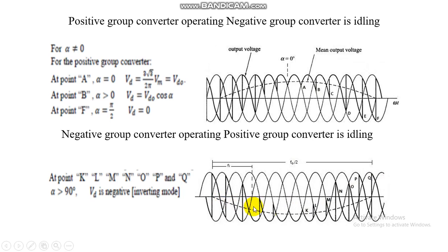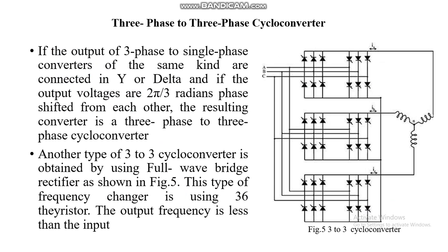With that, when we take the average of this is the value. This is the positive half cycle. This is the negative half cycle. Combinedly, we have the one full cycle having the huge time period. Thereby, frequency is going to be reduced, called step down cycloconverter.